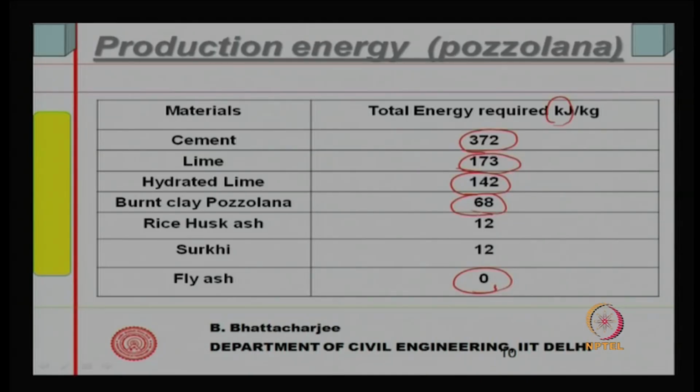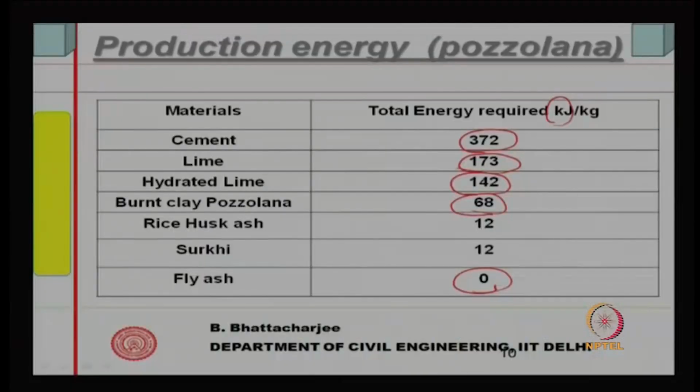When you make bricks, we have clay which we mold into bricks, and when you heat up, the fine powder as dust which comes down at the bottom of the kiln is nothing but clay heated up to 1200-1300 degrees centigrade and cooled rapidly. Surki is also a pozzolana, surki as we call it. So, surki could be one of them.